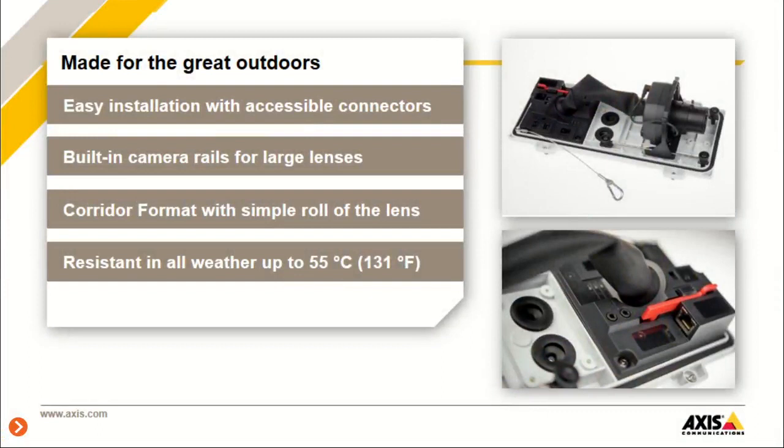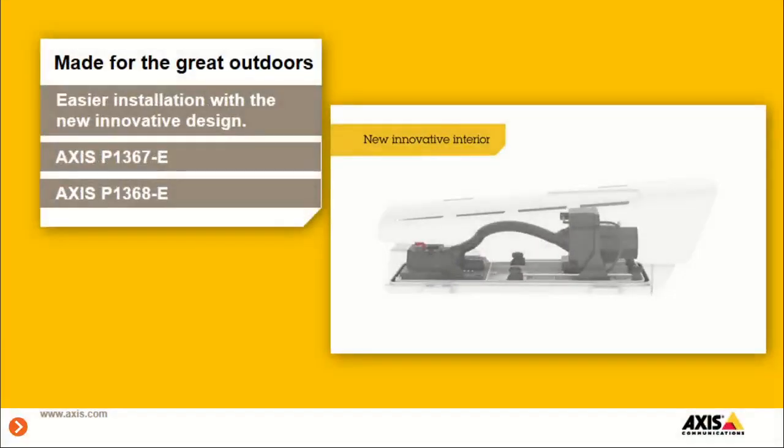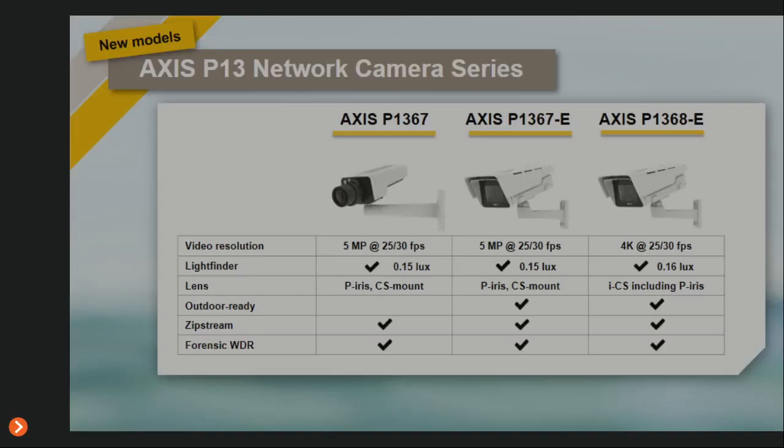It's an IK10 tool, and if you use this, you can make sure that the lens is cleared from the glass, and we can guarantee an IK10 vandal resistant rating. So also on that part, if the camera needs to be vandal resistant, you can take this into consideration.